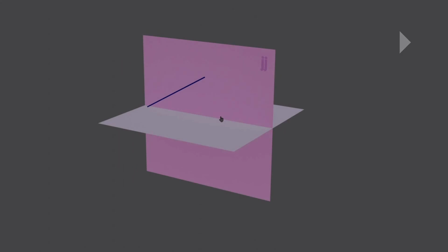See the top view. This line is actually the top view, and in the top view you can see that this line is parallel to the vertical plane. So the line is actually parallel to the vertical plane and inclined to the horizontal plane. Now let us move on to the three-dimensional view, and then let us make the orthographic drawing. Okay, now I'll switch on the lights, make the markings, draw the front view, draw the top view, and mark A prime, B prime, etc., and then we will see the orthographic drawing.